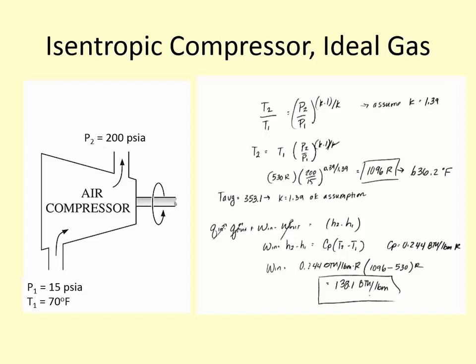Then you go through, you calculate, and you solve for your temperature. And you look at that temperature and say, my actual temperature is this. I'm going to now calculate the average temperature and look up K at that temperature and see how close I was initially. If you're close enough, you just use it. If you're pretty far off, you have to redo your calculation. Yeah, but it's not interpolation, it's just average, right? You can do it either way. You can either look it up at the average temperature or average the C sub P values.